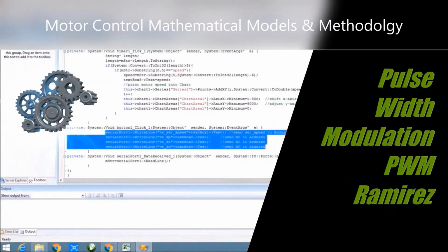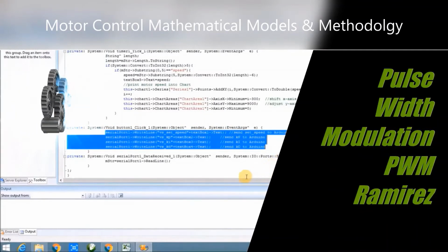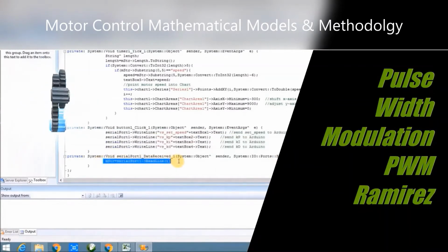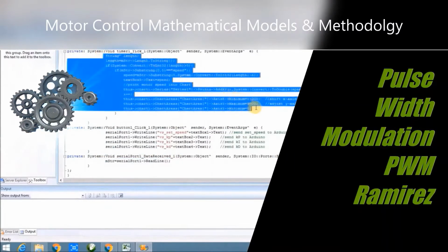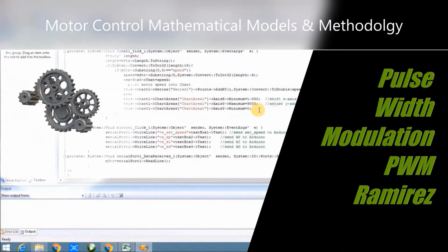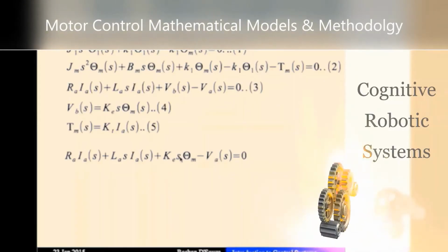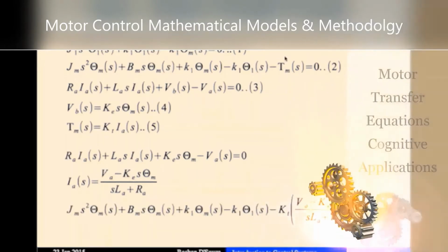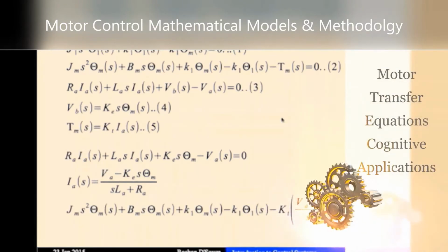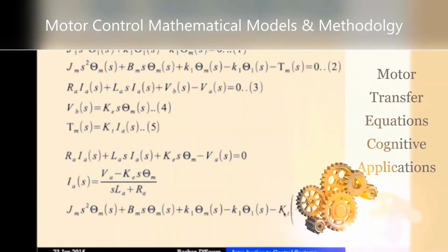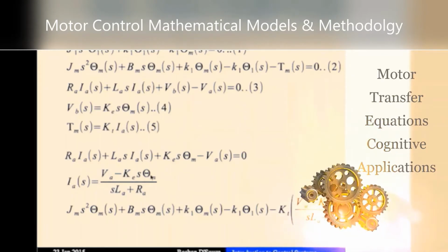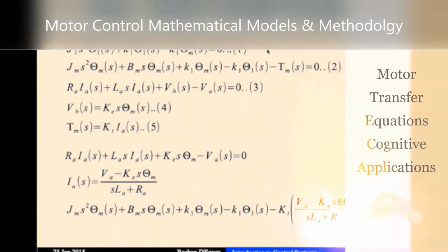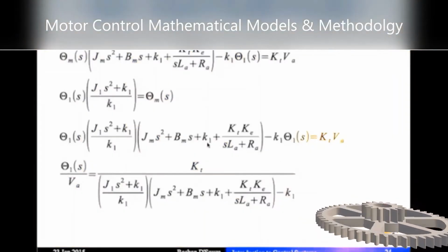In this application, the pulse width modulation duty cycle is used to vary the speed of the motor by controlling the motor terminal voltage. The motor voltage and revolutions per minute are obtained at different duty cycle rates. As the duty cycle rates increase, more voltage is applied to the motor. This contributes to the stronger magnetic flux inside the armature windings and the increase of RPM.